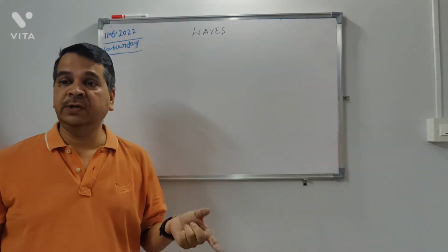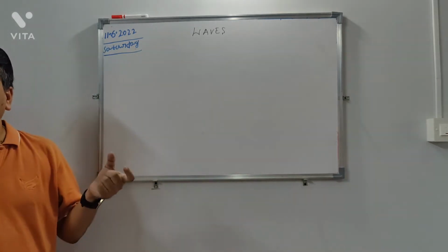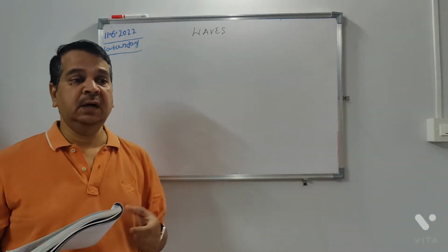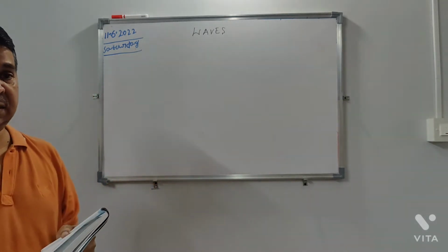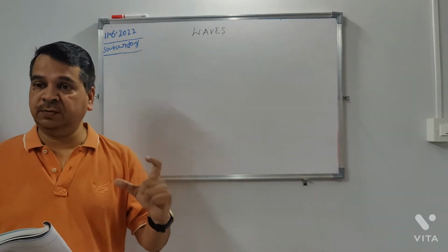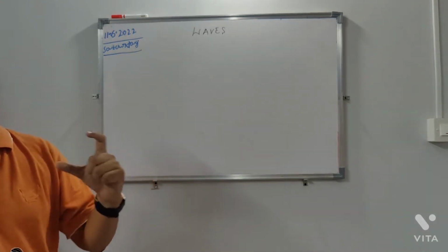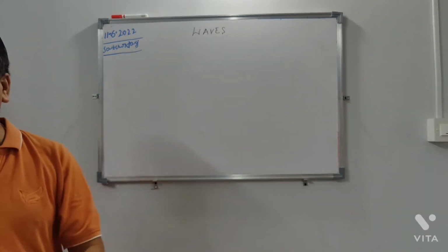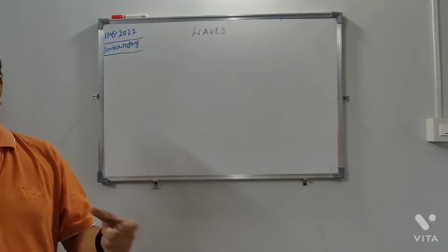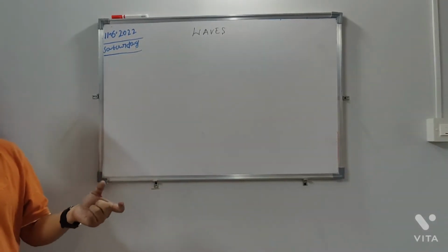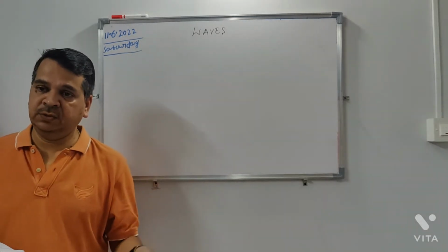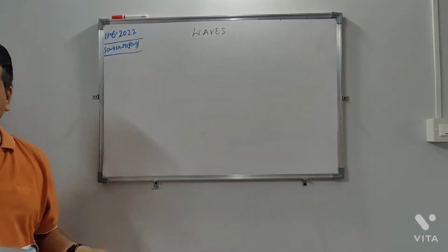So the coefficient of performance here will be, like, how much heat you are taking. So it will be Q2. Q2 is how much you are taking and how much work you are spending for that. So the coefficient of performance will be Q2 by W. Okay. W is again Q1 minus Q2. So it will become T2 by T1 minus T2.